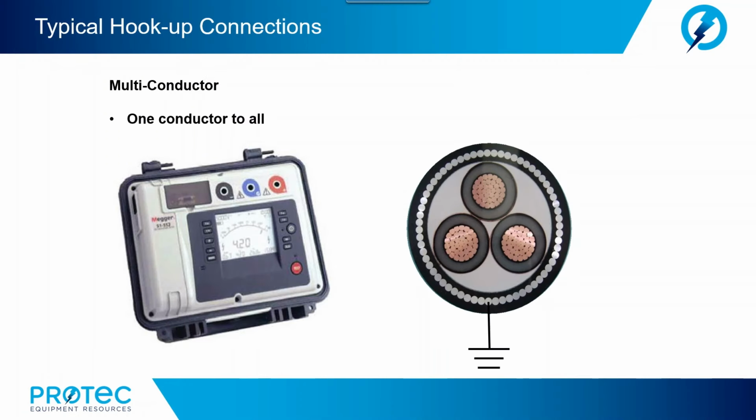Now, for a multi-conductor cable, where we have multiple conductors in the core, we can use a combination of connections depending upon which aspects of the insulation we want to measure. So, first, if we want to measure one conductor to all of the other, let's just say metallic surfaces, we can jumper two of the internal conductors together.